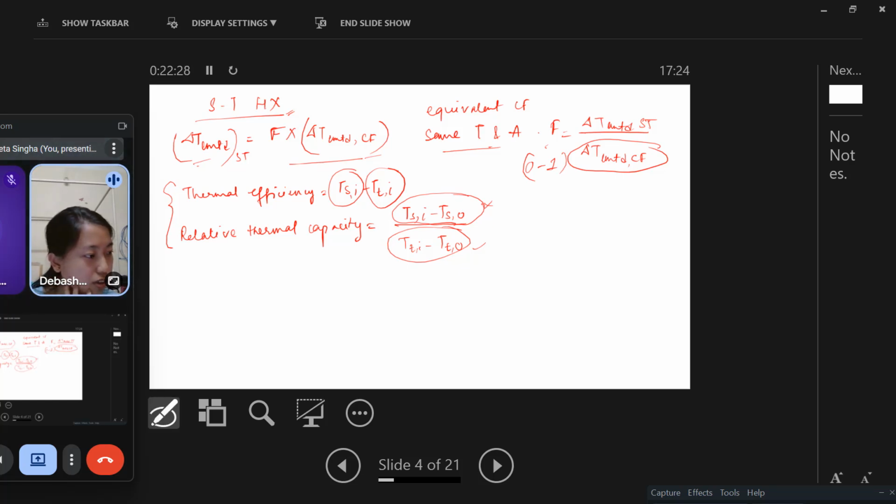Yeah, so this can also be written as MCP tube side and MCP heat capacity of the shell side fluid. Okay, so if you go with this LMTD method to find out the area required for the heat exchanger, that may be cumbersome because it follows an iterative method.